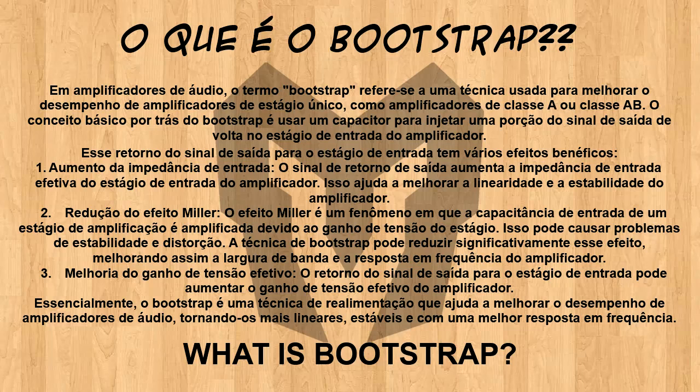2. Reduction of the Miller effect. The Miller effect is a phenomenon in which the input capacitance of an amplification stage is amplified due to the voltage gain of the stage. This can cause stability and distortion issues. The bootstrap technique can significantly reduce this effect, thus improving the bandwidth and frequency response of the amplifier. 3. Improved effective voltage gain. Returning the output signal to the input stage can increase the effective voltage gain of the amplifier. Essentially, bootstrapping is a feedback technique that helps improve the performance of audio amplifiers, making them more linear, stable, and with a better frequency response.